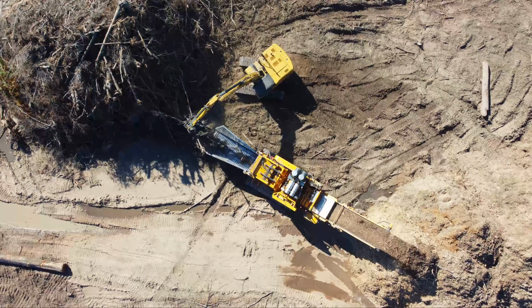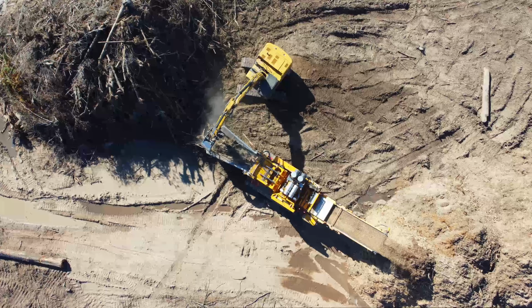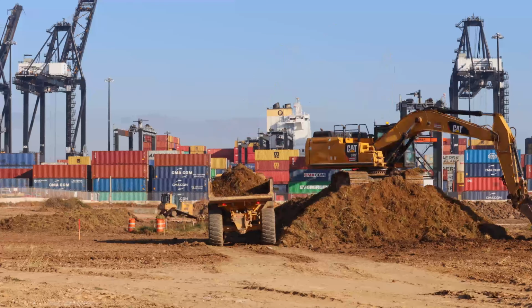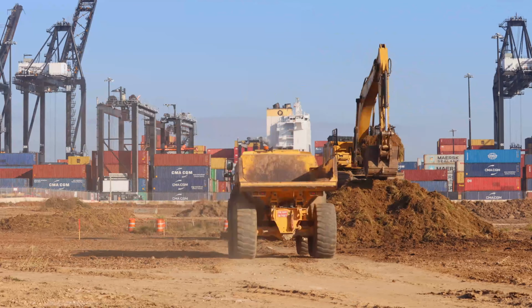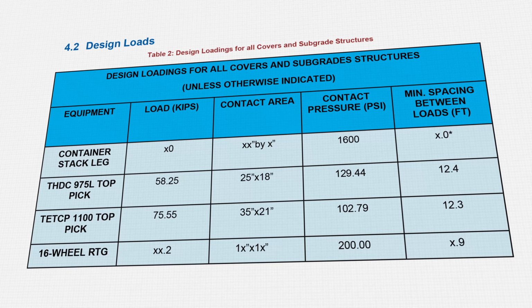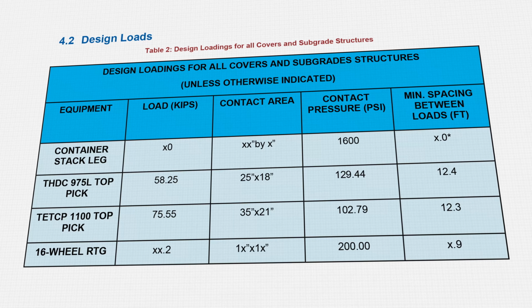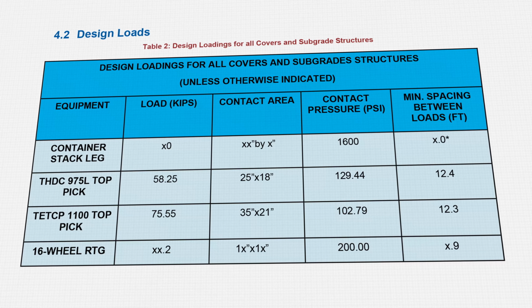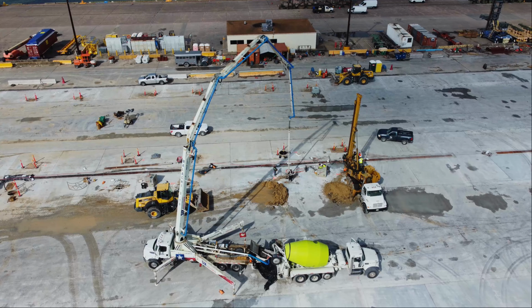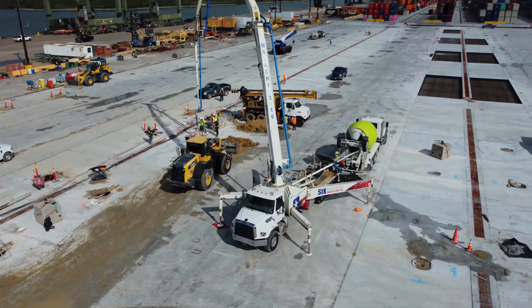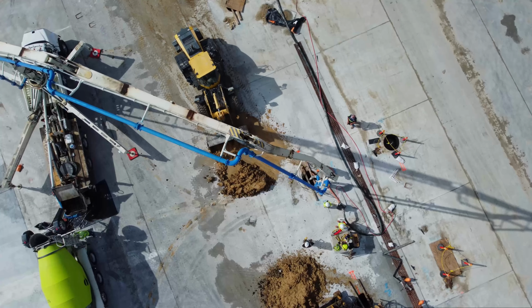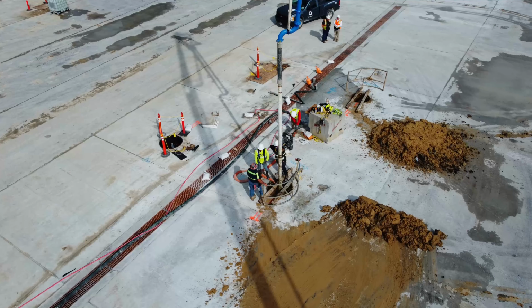Before design work begins, certain basic input data needs to be collected by the engineering design firm. This data defines requirements for the project and is provided by the owner of the project. In addition, engineers obtain design loads and criteria, such as specific dimensions that need to be met, wind load, and so on. Finally, any additional owner's wishes are gathered. For example, the owner may request that all exposed steel must be galvanized. With this information, design work begins.